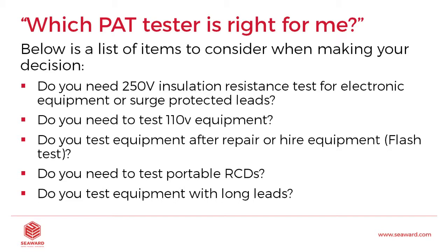Another one that's becoming very common now is RCDs. If you have plug-in RCDs or RCD protected extension leads, part of the PAT test procedure in the IET Code of Practice is that you actually carry out the trip time test of that RCD.